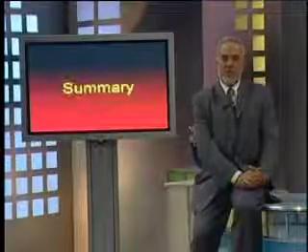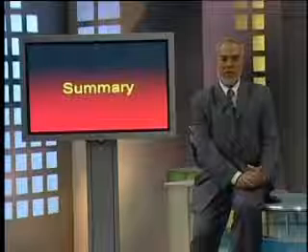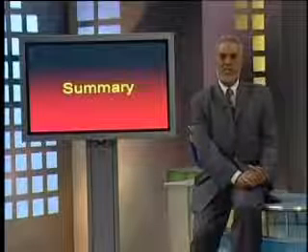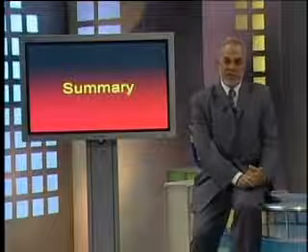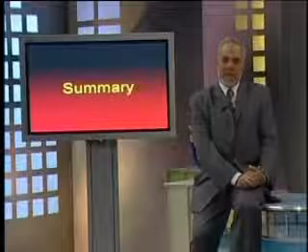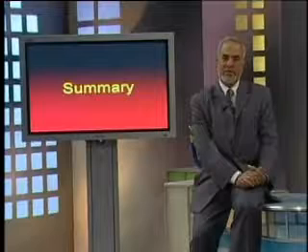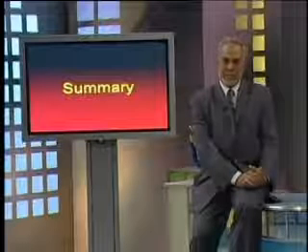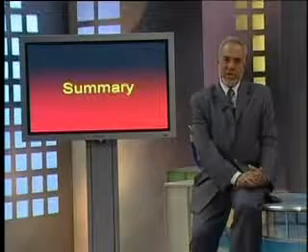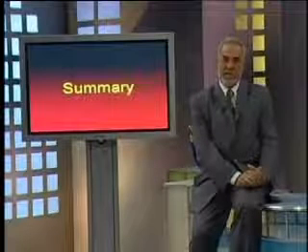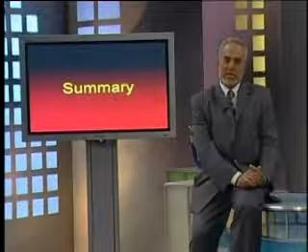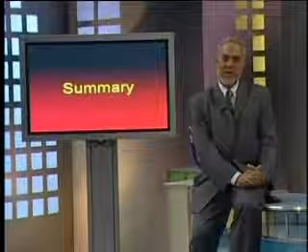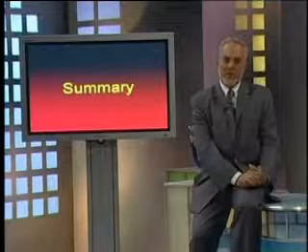Today we have considered an example of mapping an input port and discussed the decoding of the address. Then we also discussed the memory mapped I/O with reference to our Falcon A processor. We also went into some discussion of the data bit multiplexing, and we tried to economize on the address space, and we just tried to utilize all even as well as odd addresses.